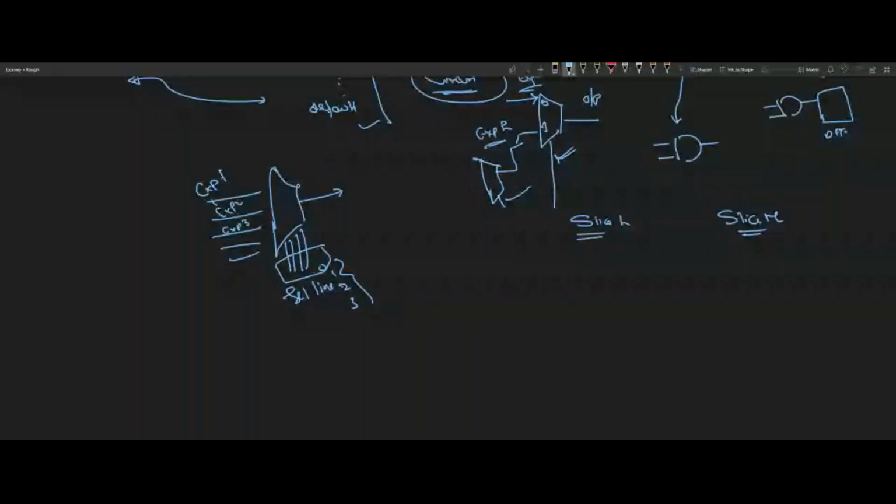Memories and shift registers are limited, right? How many shift registers can you have? In the whole FPGA itself, we will not have unlimited shift registers, the whole FPGA will not have unlimited memories. If you have some big circuitry for storing some configuration, you may have a small memory for that. That's where we have limited SLICEM.